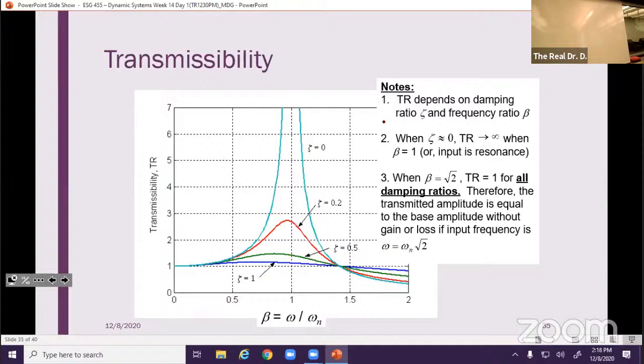This is the Tacoma Narrows bridge. If we operate near resonant frequency, we get an amplification of our vibrations, right? And if you don't change that, you will continually amplify your vibrations until you shake it apart.